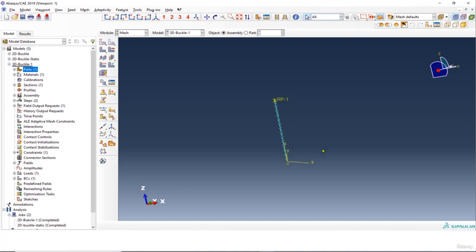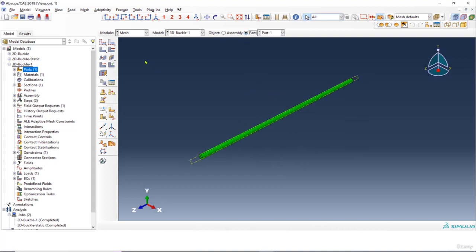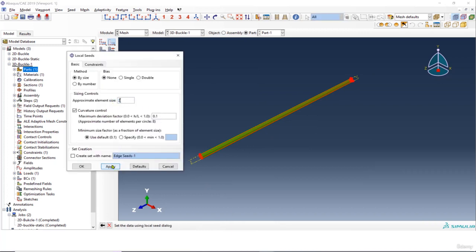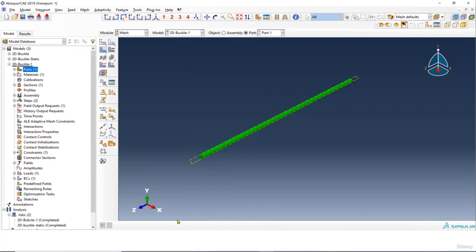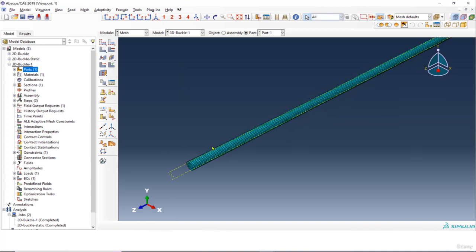And then the next step is to basically apply a mesh. Go to the mesh section and go on a part, so this is green, and select everything, click on OK, and apply 2 and assign a mesh. So the 3D analysis is going to be mesh sensitive. If for any reason, such as not using an educational license, you have to apply a coarser mesh because you're limited with 800 nodes, then it's possible that you are not going to get the accurate result, because the 3D result, as I said, is very sensitive to mesh.